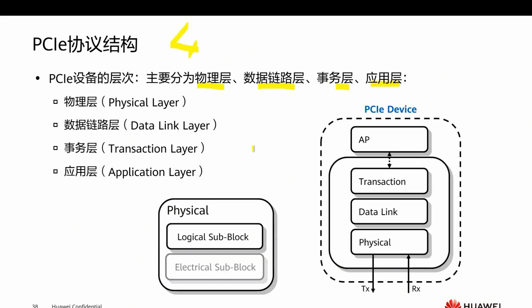The important role of the data link layer is to ensure the correctness and reliability of the data packets transmitted by the PCIe bus. It will check whether the data packet encapsulation is complete and correct, and whether the serial number or redundant transaction code is added to the data and sends it to the data protocol. It is also a designated standard and a designated protocol.